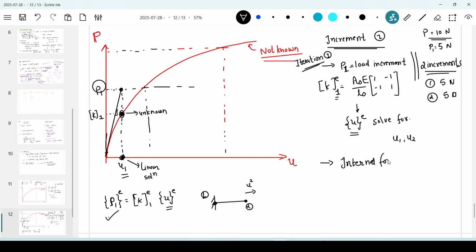Maybe it's like reaction force. Not in this case; we can say yes, reaction force for this case, but in general FEA the reaction forces are different and internal forces are different. Reaction forces you will get only where there is a boundary condition, where you fix the constraint. Internal forces you will get for all the elements, irrespective of whether boundary conditions are given or not, because when we have this structure, you have elements.